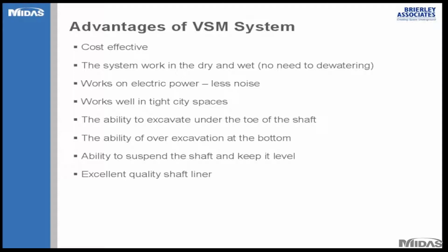The system worked, as I said, in the dry and wet, so no need for dewatering, which was a concern here because the groundwater at this site was polluted. So no dewatering at this site. And this system can work on electric power, so you don't have as much noise as a diesel engine. This is critical if you are working in the city or in any urban location. Also, as I said earlier, the footprint of this system, the setup, is really small. It doesn't take a huge space to set up the system.